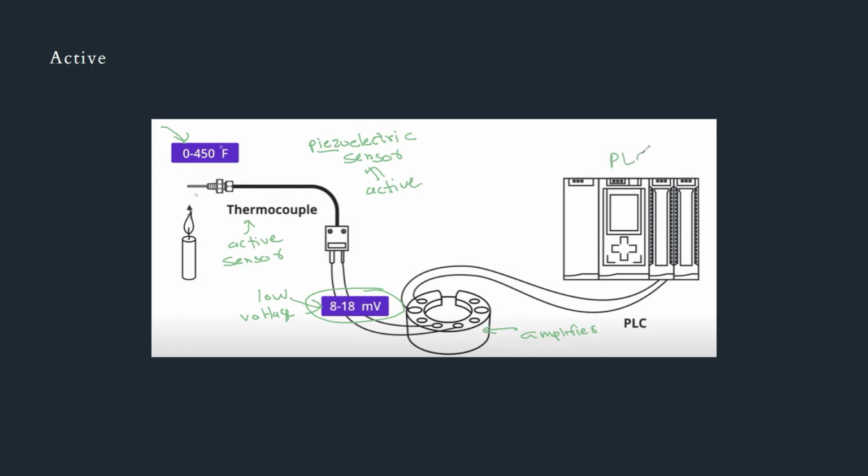So this is a PLC system. The PLC system wants to know the temperature of a certain environment. So that temperature data will be fed into this PLC through these thermocouple sensors, and the transmitter that amplifies the thermocouple output and provides it as a considerable voltage to the PLC. And so the PLC will receive temperature data through the thermocouple, right? So that is basically regarding the thermocouple.